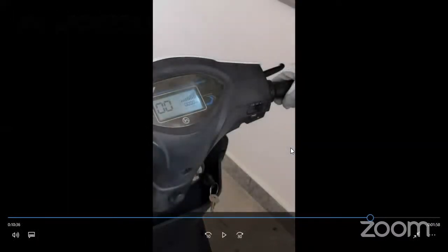So I've connected to our test vehicle. It's in discharge mode. Again, for the discharge, just to show an example, I've given a maximum of 1 amp. The load should withdraw, right? The max the battery pack can give is 1 amp. Above that, if the load is asking for more current, then it should cut off. So we'll just look at it.